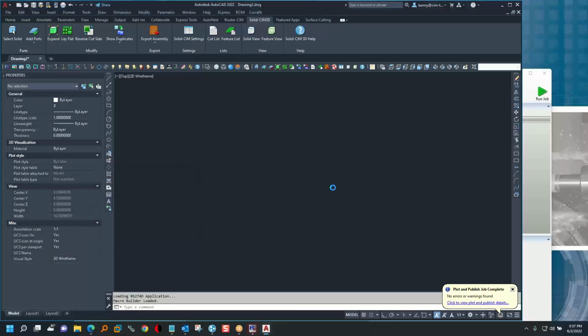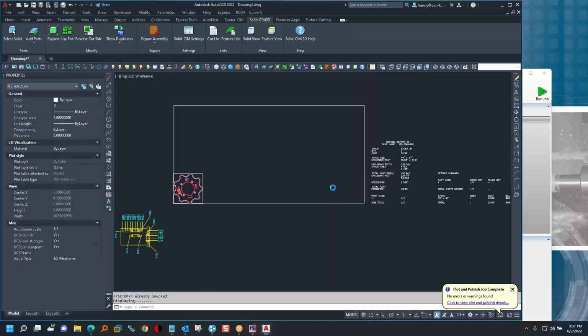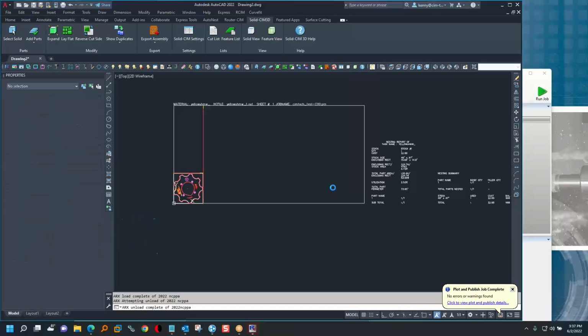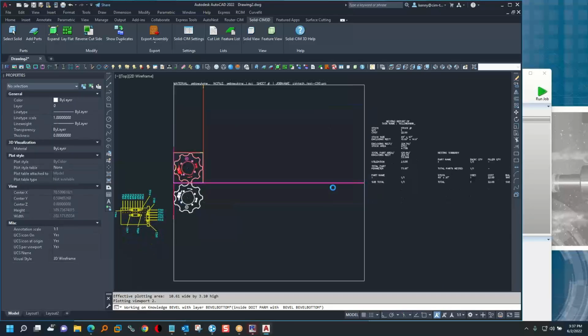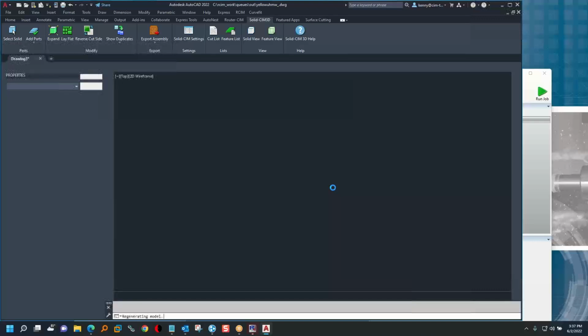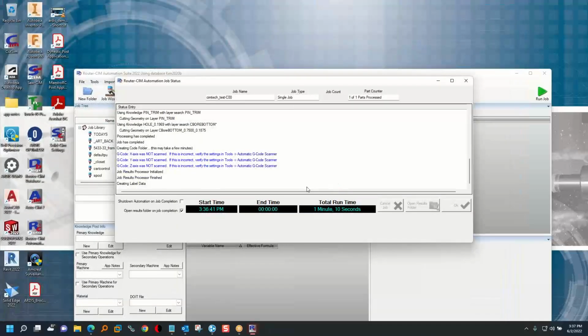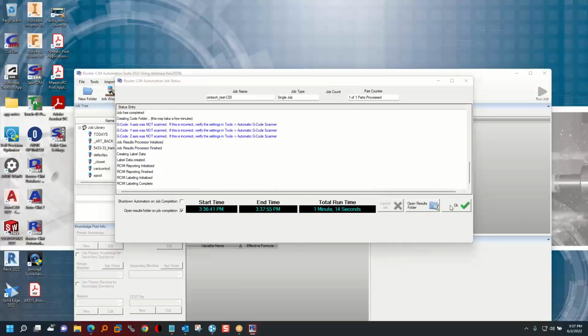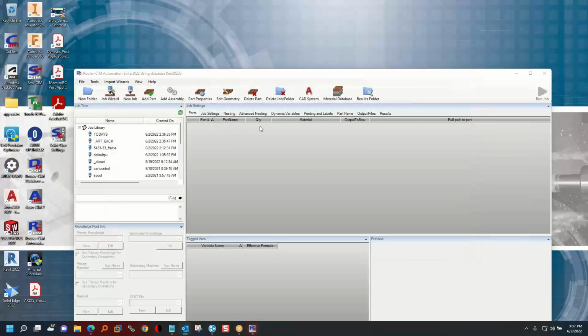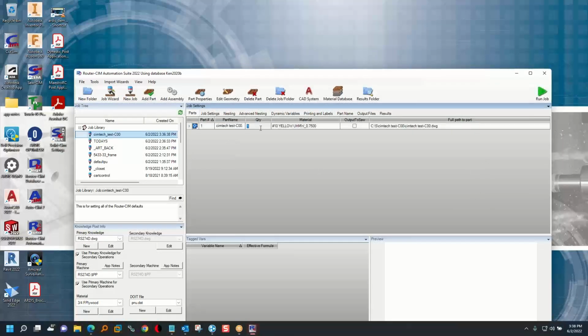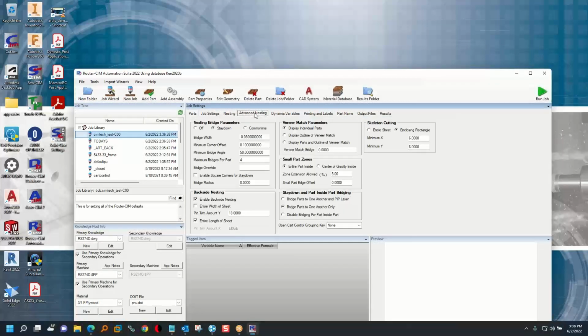And there was just one of them in this example. I could have copied it in SolidWorks to get quantity 2. Or I could have changed the cut list so it said quantity 2. Or now I'll change the job to quantity 2. Sorry about that. I should have remembered that, but I did not. But here it is here. Quantity 2. And I do have this set for backside nesting.